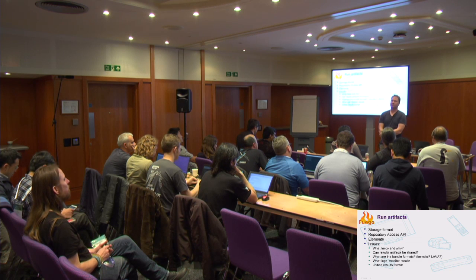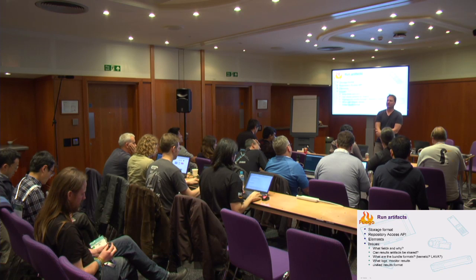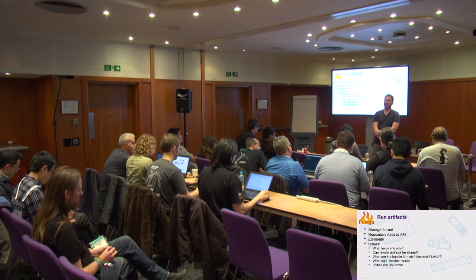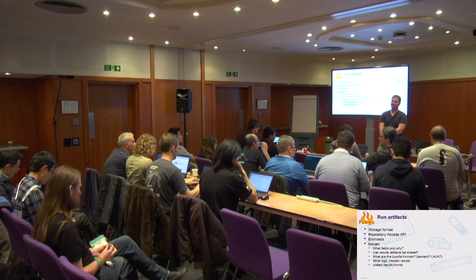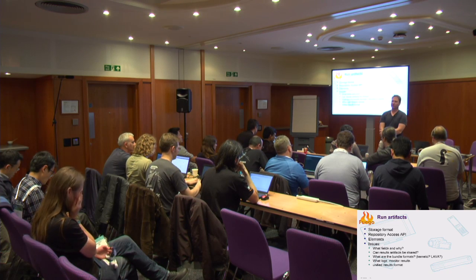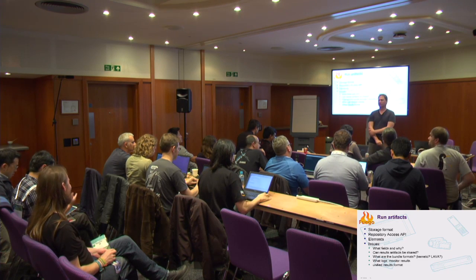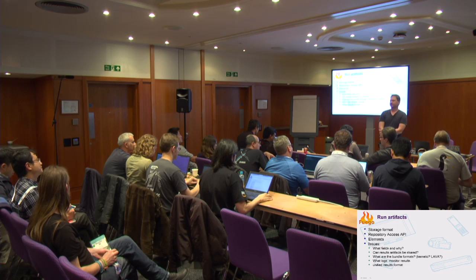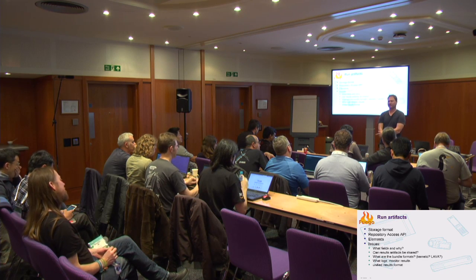I mean, you have test failures and non-test failures, but I think a lot of people have different terms for all the various things that can go wrong. Lava just calls them all infrastructure errors, but they each have types of categories, like your networking failed, or your U-boot didn't actually come up, or your PDU didn't actually reset your board, or all these types of things. But it's nice about VMs, you don't have to worry about some of these things.